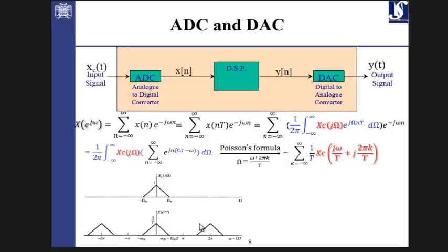Considering that this is continuous in time, you can bring it back with this integral, which is the CTFT synthesis form, and you get this X continuous of j omega. So that's the CTFT of a time domain signal. And instead of continuous time t, we just replace it with nT. So t is replaced with nT. So that's what we have.